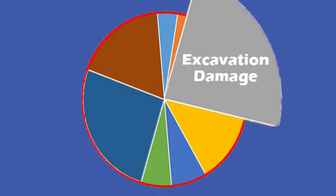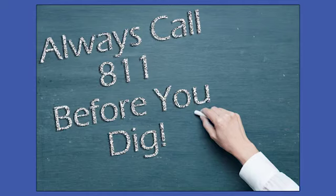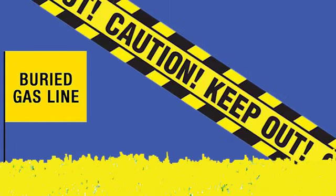But I do know that another cause of reportable incidents is excavation damage. To combat this, the industry is working collectively to educate excavators and the public about the importance of calling 811 before digging. Also, all operators must make sure to mark the locations of buried pipelines when requested by an excavator, install above-ground line markers in certain locations, and take extra precautions when working near critical facilities.